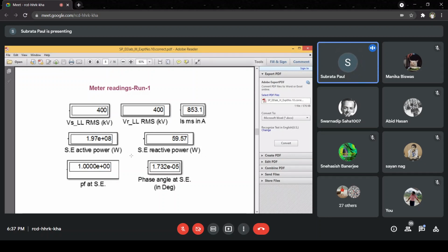Actually, it is simple. You see, if no reactive power surplus is there, that means at every point the reactive power generated by the line is being absorbed by the line at that point itself. That means the sending end also doesn't have to deliver any reactive power to the line, isn't it?